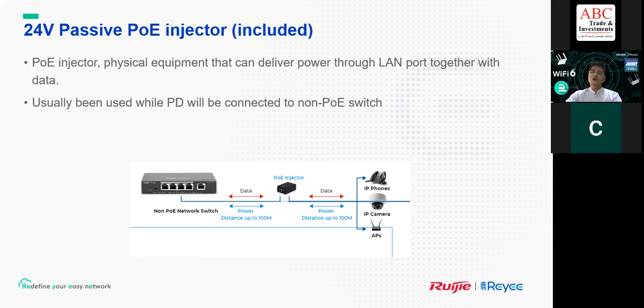Okay, so I will go to another topic. I want to explain a little bit about passive PoE. The passive PoE we support is 24 volt, right? 24 volt. So our product, the EST310 or 350, only supports passive PoE. It does not support standard PoE. So what's the difference between standard and passive? Passive has no guarantee for the power issue.